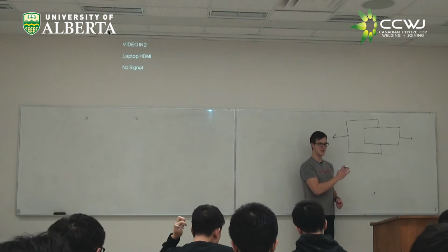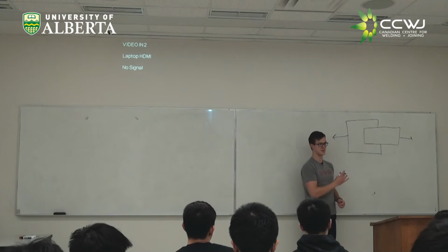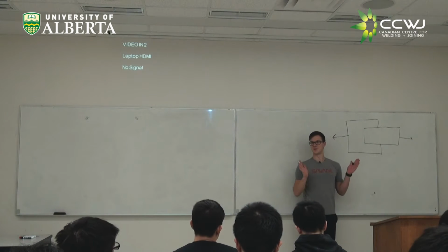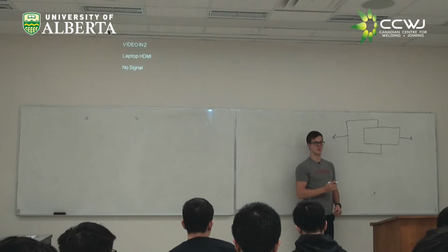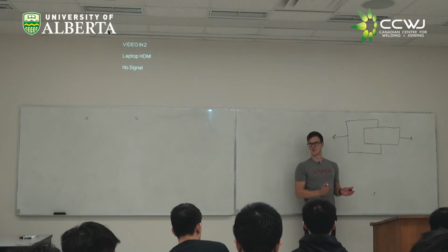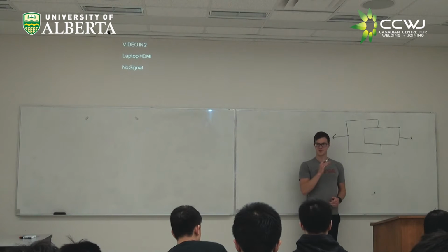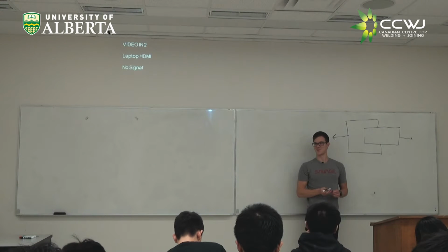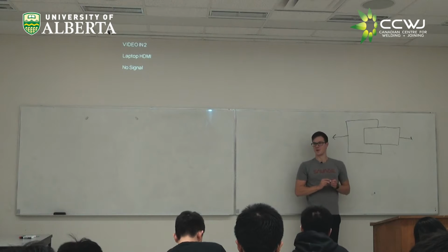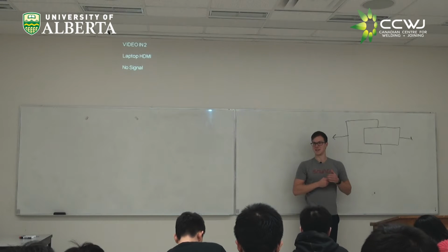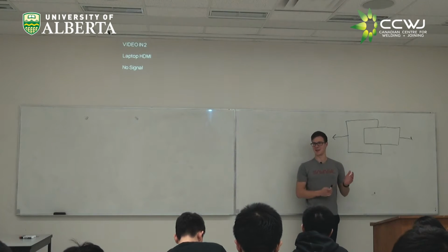At the very end today, we talked about the formulas for tension and the formulas for shear. There was no difference between the two of them, right? You have a load, you divide it by an area, ended up being exactly the same. We're still using the throat area. There's some amount of conservatism in there because you probably know that if you load something in shear and you load something in tension, you might not fail along exactly the same path.